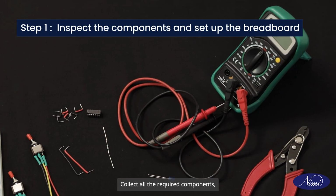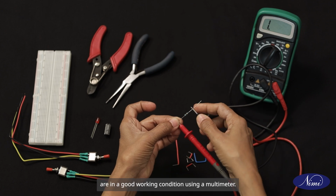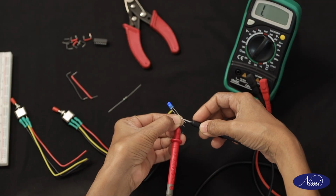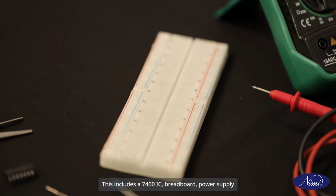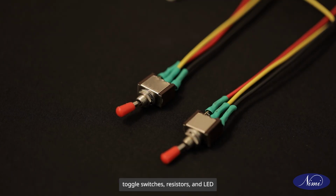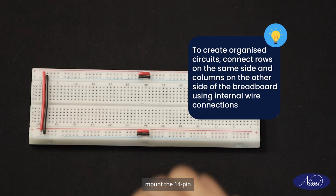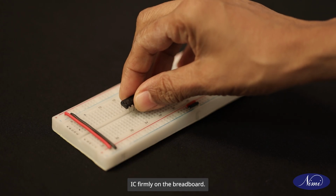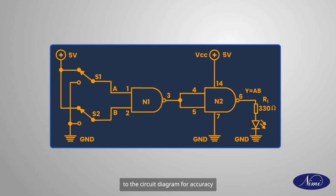Collect all the required components. Check them. Ensure the resistor and LED are in a working condition using a multimeter. This includes a 7400 IC, breadboard, power supply, toggle switches, resistors, and LED. Once you've got everything, mount the 14-pin IC firmly on the breadboard. You can also refer to the circuit diagram for accuracy.